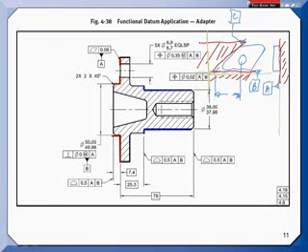If I build a fixture, I'd put a chunk of steel right here in that fixture so I could touch off it with a probe to come out to measure that hole, find out where that hole is, because my origin of measurement's back here. So I think this kind of shows the difference between datums, which are theoretical and perfect, mutually perpendicular, datum simulators, which are your setup, and then your datum features themselves, which are the crummy things on the part. I don't know if that helped.